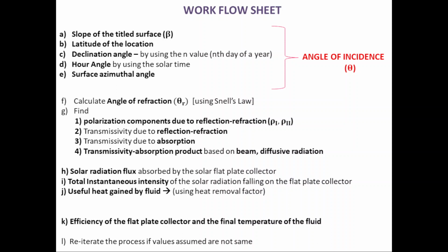So you calculate your transmissivity due to absorption by Bouguer's law, that is tau alpha equals e to the power minus K delta c by cos theta r, where again K is your extinction coefficient, delta c is the spacing between your glass covers, and theta r is your angle of refraction.